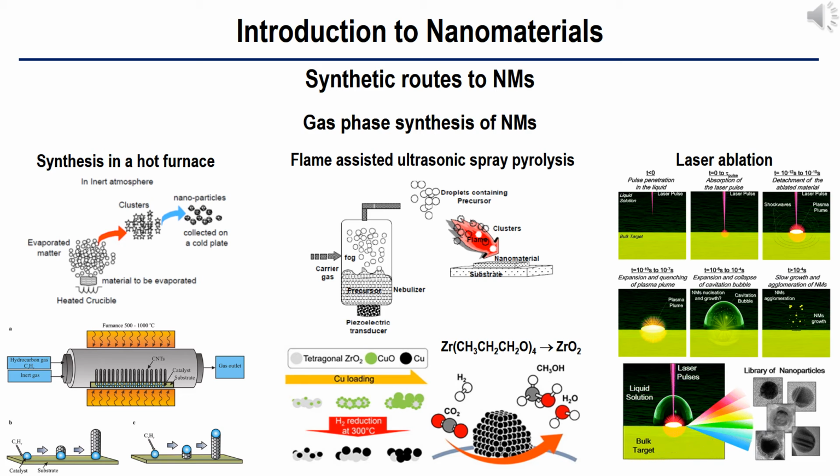The combustion flame synthesis, in which the burning of a gas mixture, for example acetylene and oxygen or hydrogen and oxygen, supplies the energy to initiate the pyrolysis of precursor compounds, is widely used for the industrial production of powders in large quantities, such as carbon black, fumed silica and titanium dioxide.